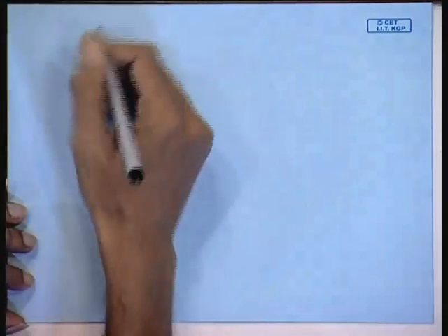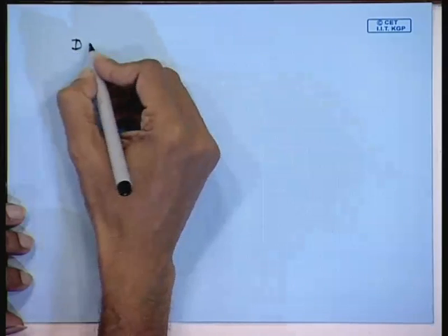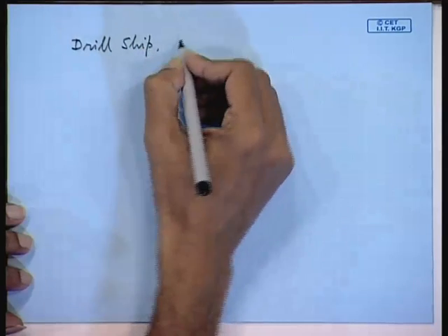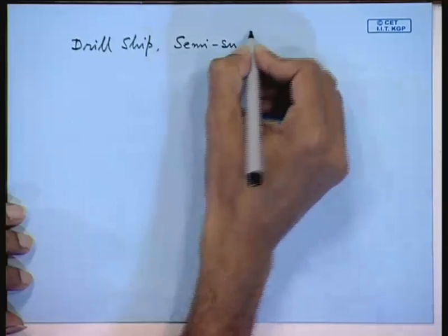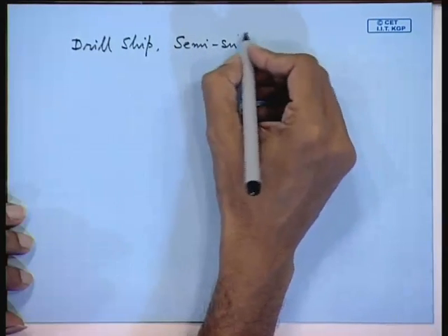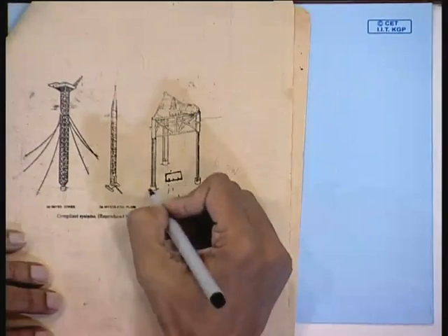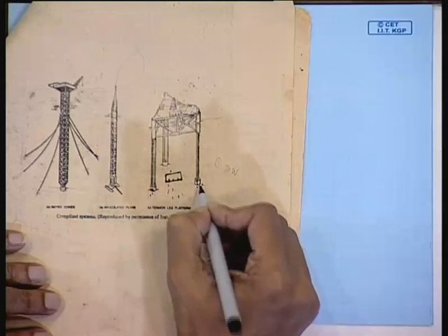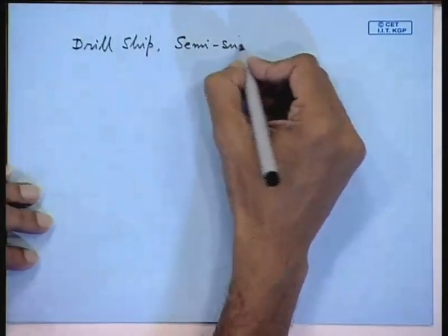Now, the floating platform, these are the compliant structures. Your drill ship is a fully floating platform. Drill ship, semi-submersibles. They have nothing, they have no connection with the seabed, whereas you can see your tension leg platform, they are tethered down by means of gravity anchors to the seabed, but these sort of things you will not find in a semi-submersible, they are fully floating.